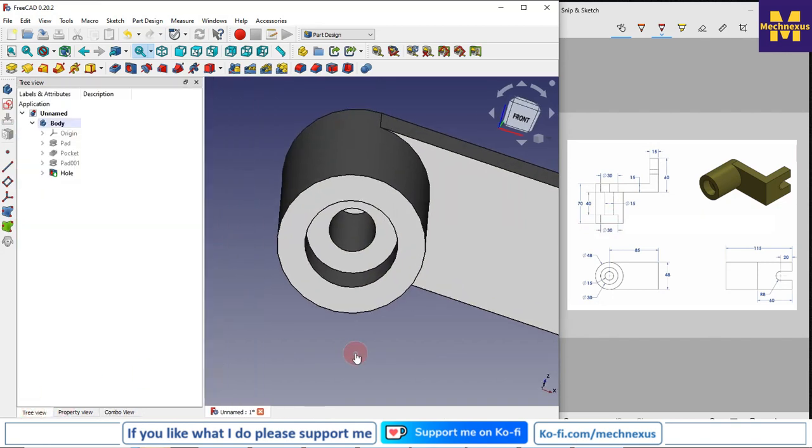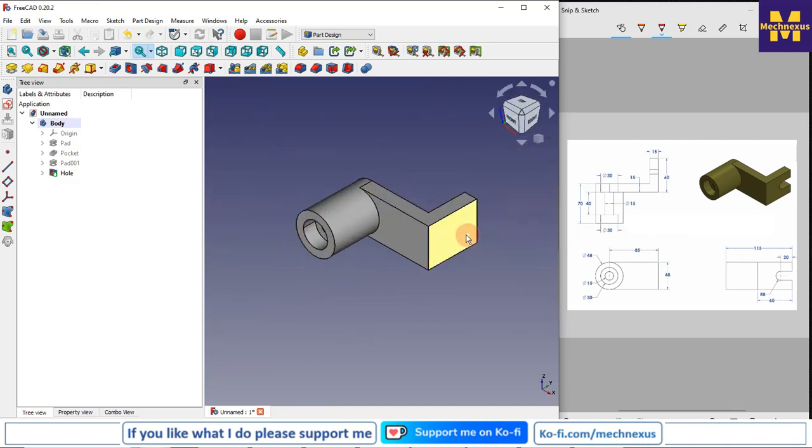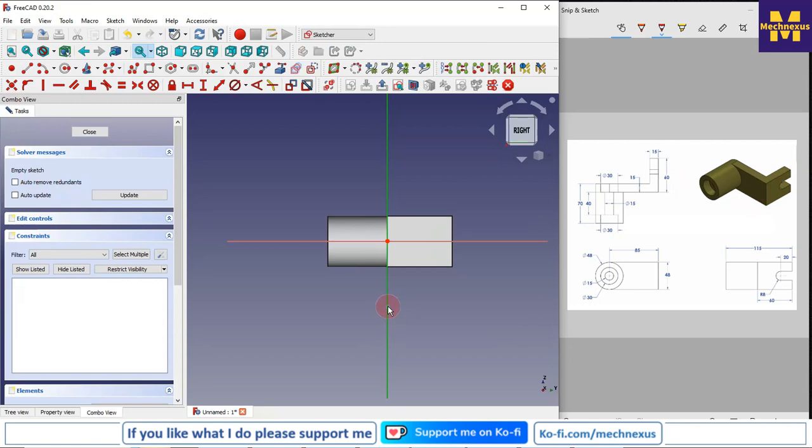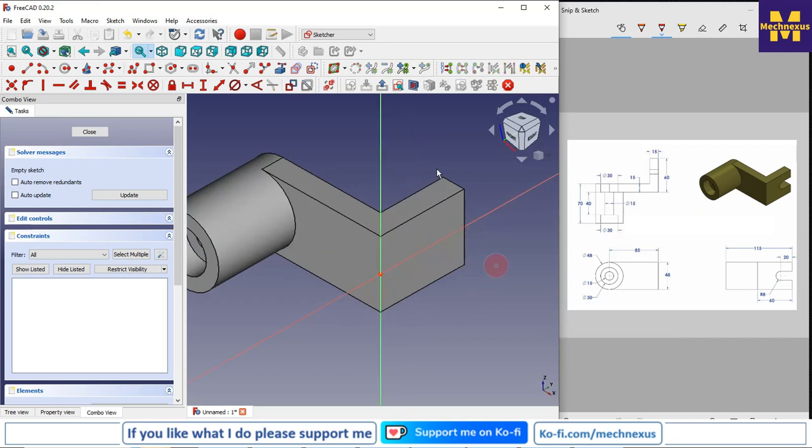Now go to the tree view. Now we will create this slot on this face. So I will select the face and create a sketch. I will convert the edge.